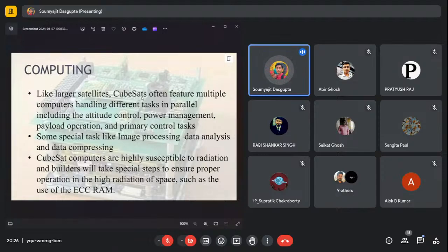Every sensor around the microprocessor will send its parameter data, like the BMP180, which can measure temperature and altitude and send the data back to the microprocessor. Then comes the DHT11, which can measure humidity. It will send the data back to the microprocessor. Like that, the data from every different sensor is gathered in the microprocessor.